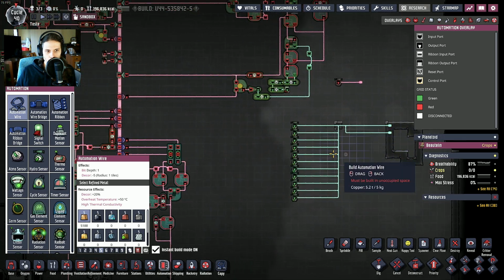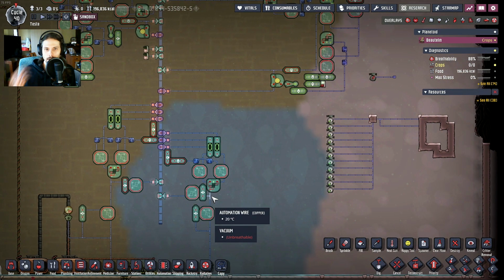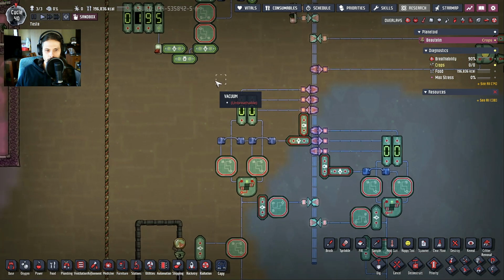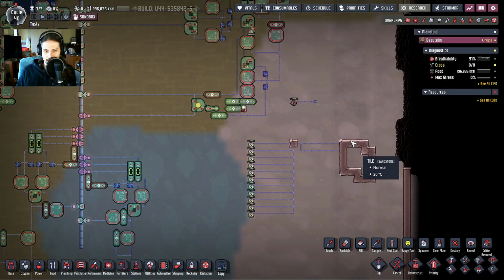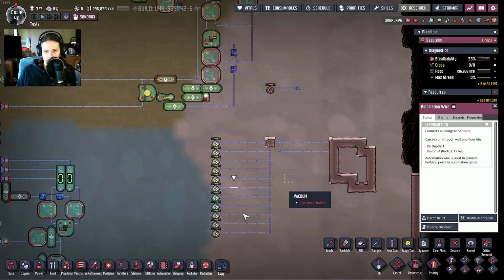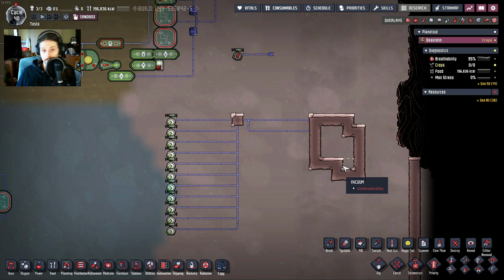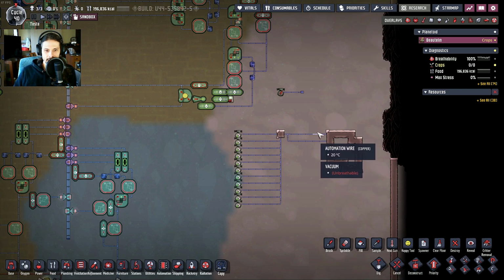Inside of the ECU, you do have, well, in older units. In newer units, they can already read digital signals, but the older units, late 90s cars, for example, usually have a decoder unit such as this to decode this digital signal back into analog, right? They go like this, and then they have an analog signal back so that the ECU can read it and then act upon it. So yeah, this is the basic explanation of what a CAN bus is.